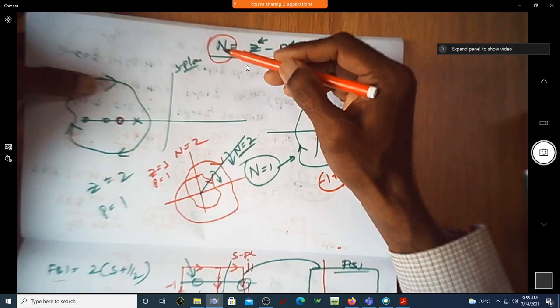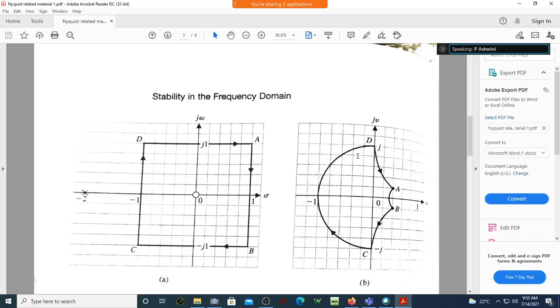Yes, sir. Okay, fine. So now with this G(s)H(s), which is 5 divided by s plus 4, I need to write the contour that will exist in the G(s)H(s) plane. Can you see this is my contour? Maybe if you just go back to our problems, can you see this was your S-plane contour, and this is your F(s) plane contour? Correct?